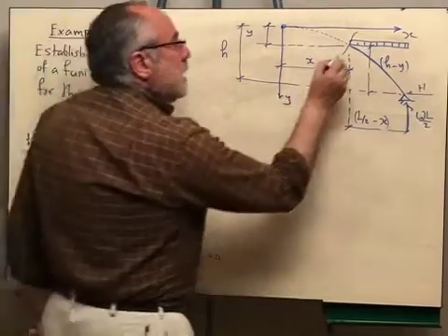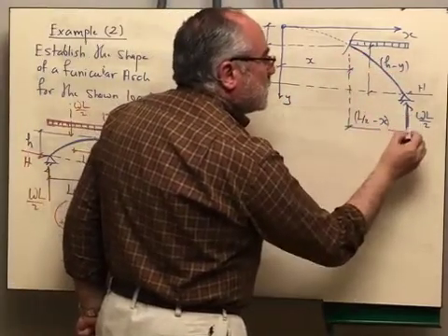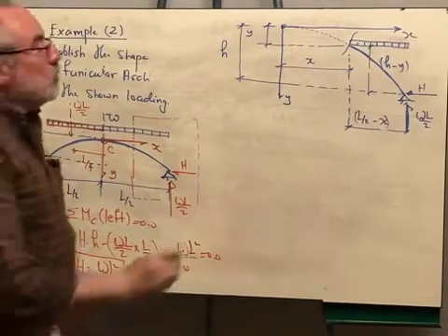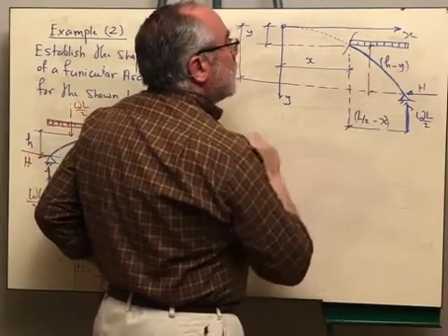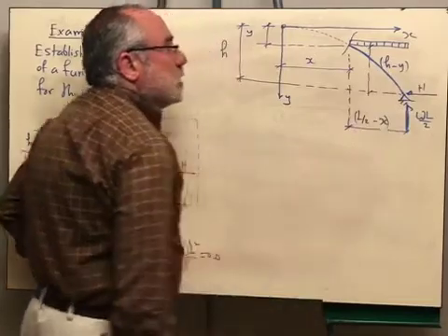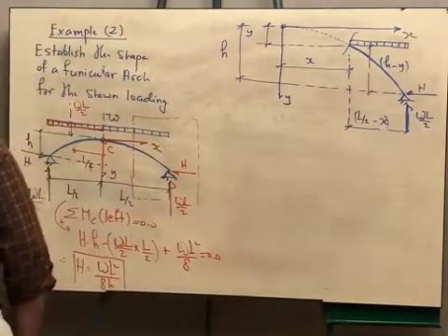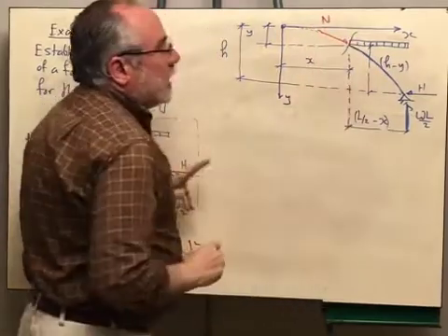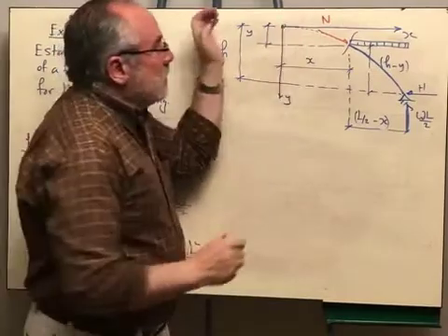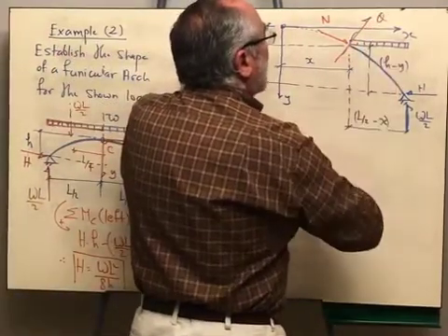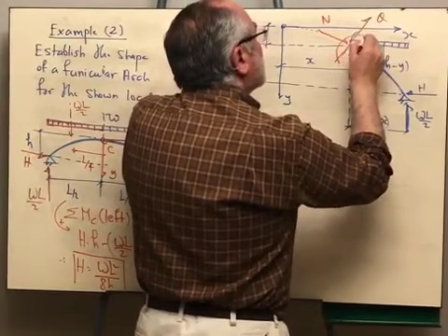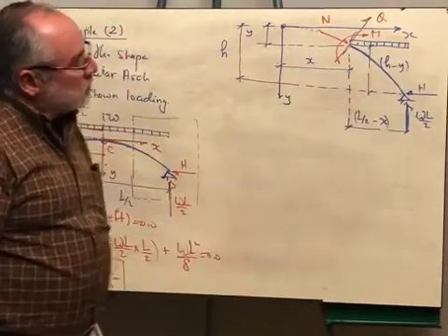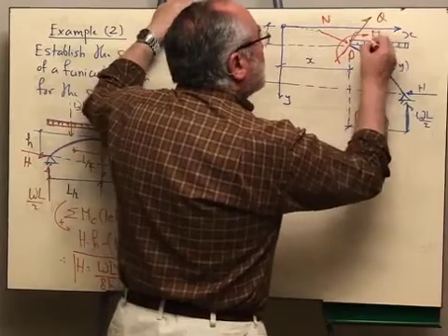Very good. So I'm taking a segment, the right hand side, the reaction is WL over 2, the horizontal reaction, we know its value is WL square over 8h, and we know the height from this point to this point is h minus y, and the horizontal distance from this point to this point is L over 2 minus x. What kind of forces do we have here? Because this is an arch, we should have compression, normal force, we should have shear. Now the cut section is on my left hand side, so the positive shear will be upward like this, and we should have bending moment. The tail of the arrow is under the datum, assumed to be positive, the moment is positive and the shear is positive. If this is point O, now I want to get the magnitude of the bending moment.